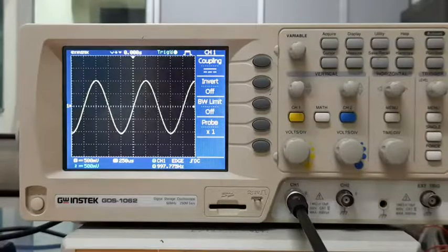And the trigger level value for periodic signals can be placed close to 0 without worrying too much about it. Okay. So these are some of the small things, some of the main things while looking at a signal. And then depending on what time and who was the previous user, your oscilloscope has many more functionalities, and there could be other things which may not have been set properly. So I'll go over one of these, and then the rest I'll cover during the experiments itself, right?